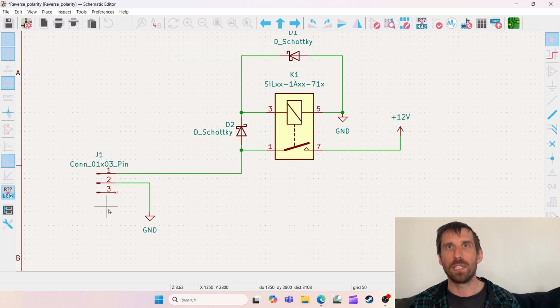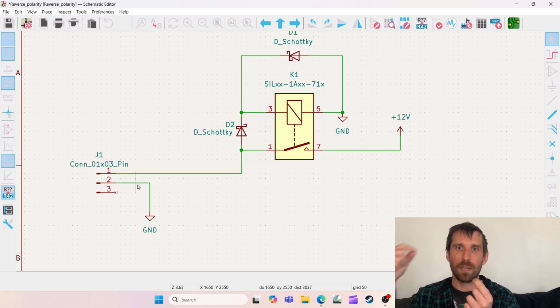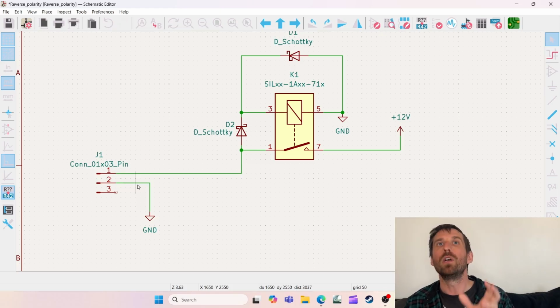That's not the only thing you need to worry about. Now, let's say this is internal to the product. So how's this cable assembly made? If it is made internally, meaning you have people in your company putting in the pins and then the wires and soldering, or crimping and all this other stuff, they're making it in your place, you need reverse polarity protection.